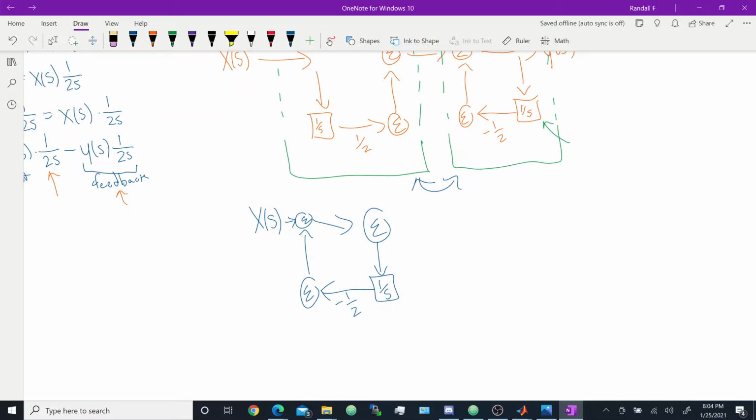We're going to lose this in a second when I click on the screen, but so we're in Simulink. How do we get started? I like to go in the library. We're going to need some stuff. Believe it or not, all these components are in the library. We have x of s and input. That's not going to be in there, but you're going to need to find some kind of source. We're going to have an integrator. We're going to have something that allows us to sum, and we're going to have a gain operator as well. So let's go into the library and find what's in there.